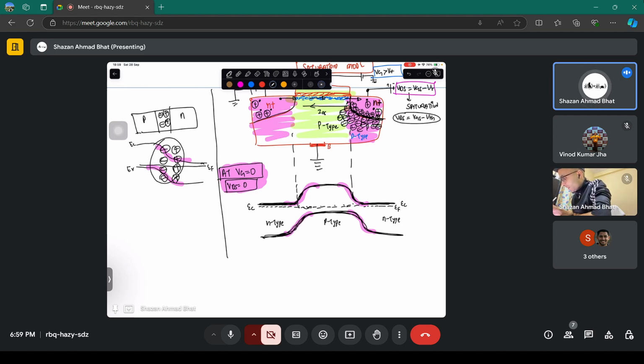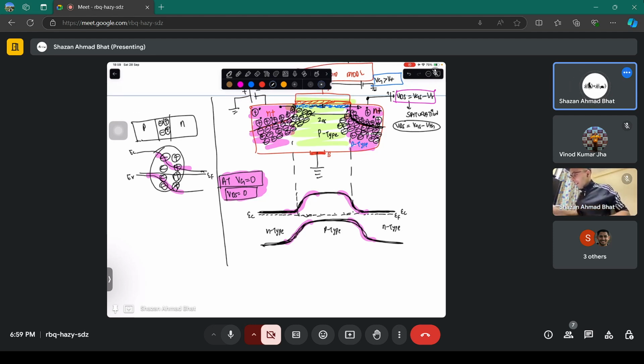So this is the depletion region. The same happens on this side. It's a very complicated scenario on this side. You have two PN junctions, but I just want you to feel like the PN junctions. If you understood PN junction, you can understand everything. These are the depletion regions, and you know how much they spread. Let me remove this color. And you see how much they spread. This is the depletion width. This is the depletion width.